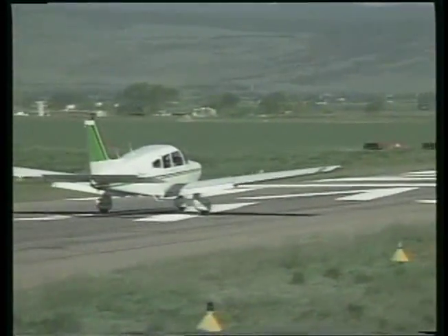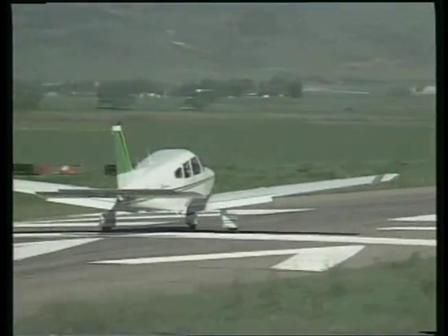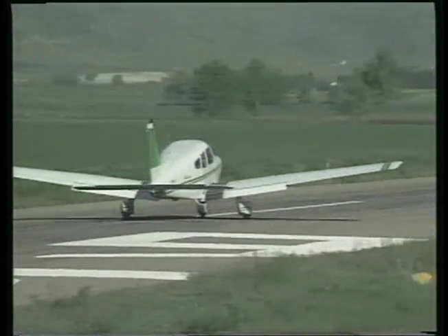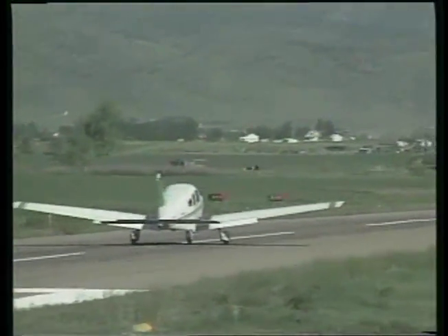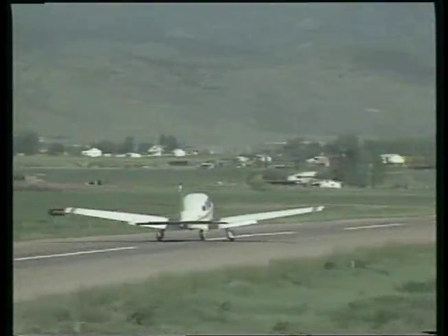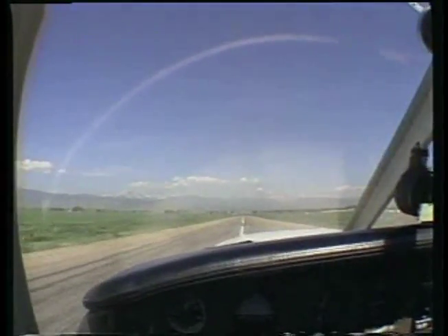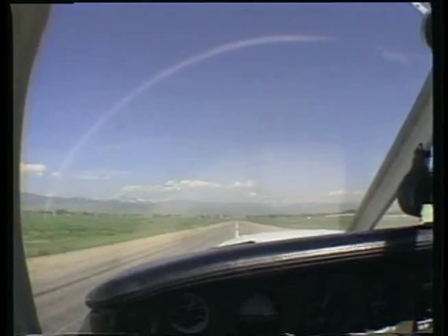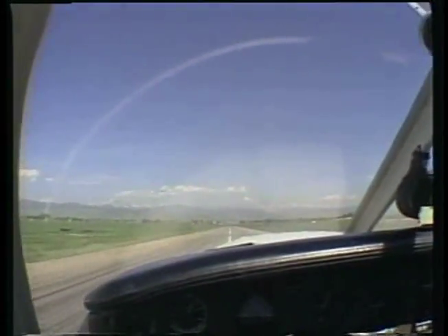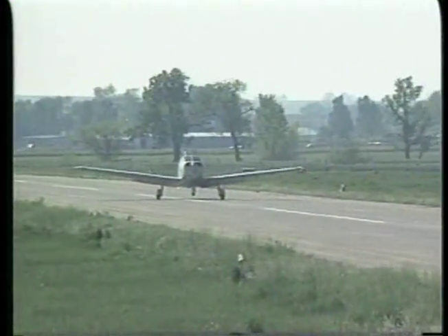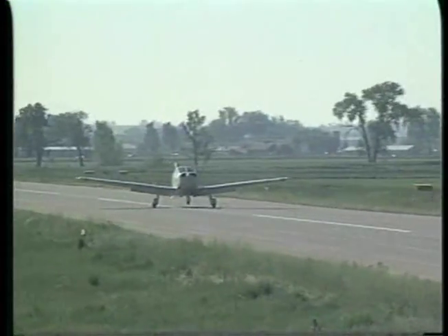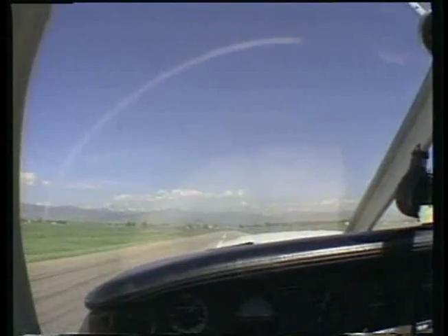In order to prevent the nose wheel from sinking into the soft runway during the takeoff roll, you need to transfer the airplane's weight from the landing gear to the wings as quickly and smoothly as possible. This is accomplished by holding back pressure on the control wheel and accelerating the airplane in a nose-high attitude. As the weight on the nose wheel is reduced, nose wheel steering becomes less effective. However, you will still have directional control because of the slipstream flowing over the rudder. You can relax some of the control wheel back pressure as speed builds up and the elevator becomes more responsive.